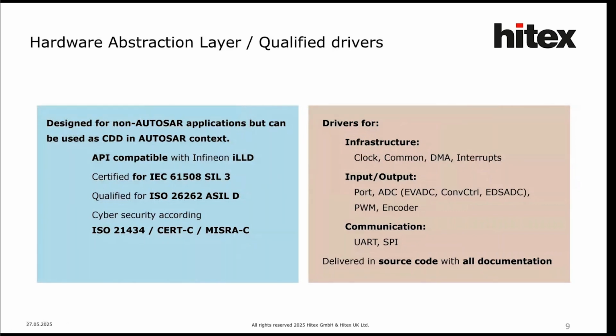Hardware abstraction layer with qualified drivers. The drivers are designed for non-AUTOSAR applications, but can be used as a CDD, a complex device driver, in an AUTOSAR context as well. The API is fully compatible with Infineon iLLD. The drivers are certified for IEC 61508 SIL-3 or qualified for ISO 26262 ASIL-D, and cybersecurity according to ISO 21434, CERT-C and MISRA-C.